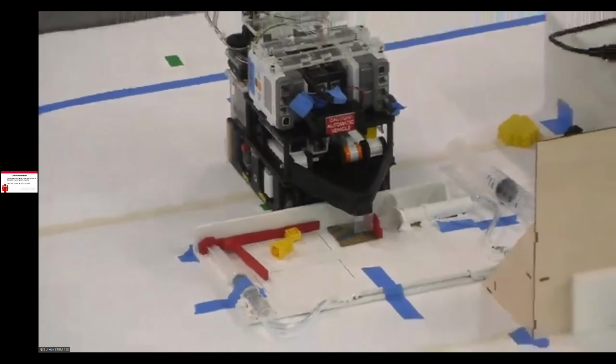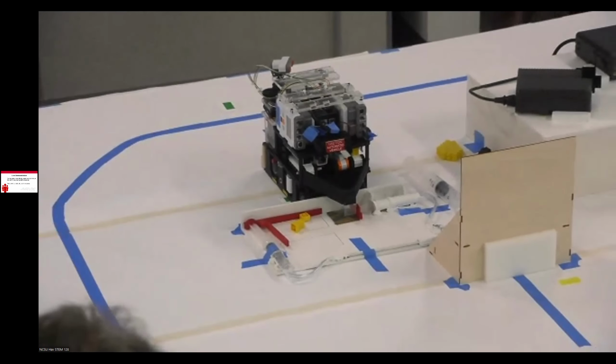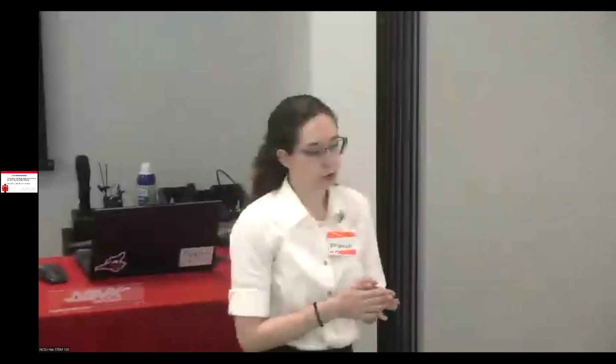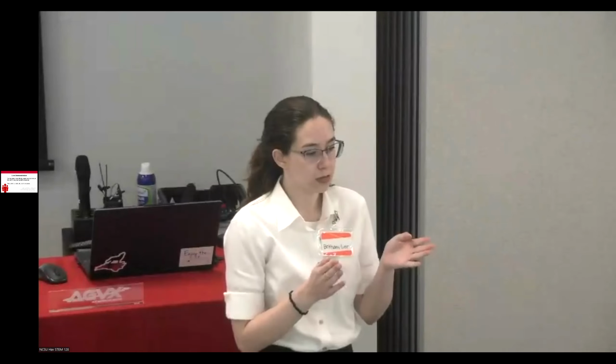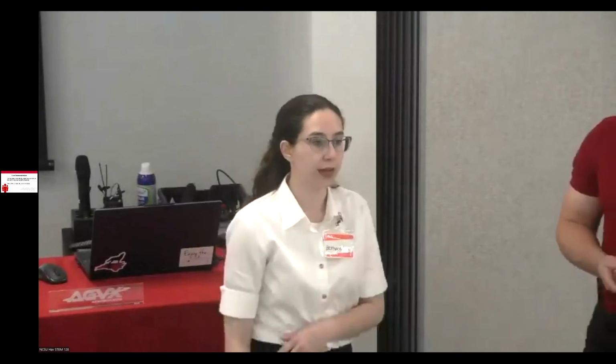There's a different color for each station. So the green is going to be mixing, molding is red, and the data is yellow. So when the color sensor drives over that, it will see the color, and depending on which color it is, it will determine which direction it will pull into the cell. And then it also determines which function it'll call, like it'll say we're at whichever station, and that determines what brick 2 will then do once we get in there.